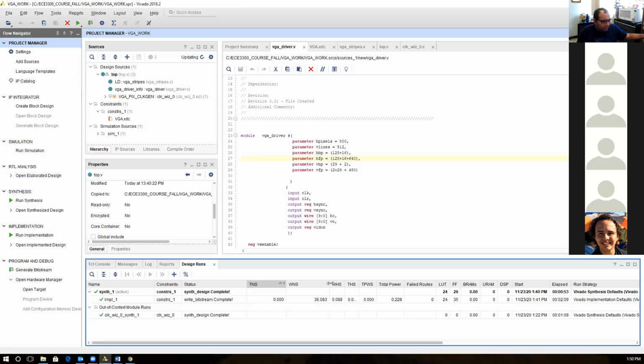Why? Because you already have the driver, right? You have the UART. You can just send the data, and you build the encoders inside, looking for the value, and from the ASCII you build the table and start drawing it, like what we did with the 7-segment display. You can also use switches to stretch it on the screen and contract it, making it smaller and bigger. There is a big room of fancy stuff you can do with this.